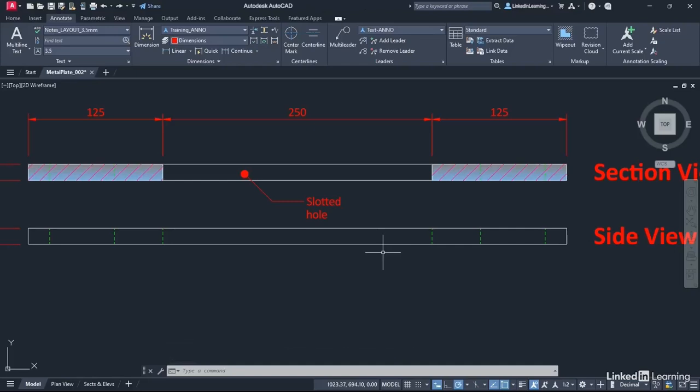That is utilizing your dimension style, and it's utilizing, as you can see, the dot that comes out of that dimension style as well. It is annotative. If you hover over it, can you see you've got the annotative symbol? Same with your other annotative dimensions. Now you'll notice there's only one annotative symbol on these dimensions because you're only using one annotation scale. If you see two symbols on the crosshair there, it's using more than one annotation scale on an annotative object.